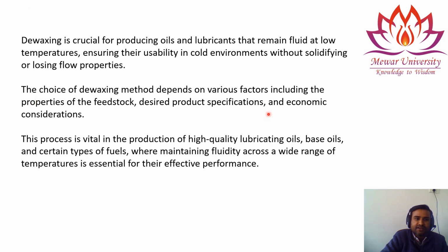In lubricating oil and base oil, removal of wax is important because once this lubricating oil is used in your vehicles, during winter or cold season you will find that your engine is not starting, because the flow of the engine oil is stopped due to wax formation at the low outside temperature.